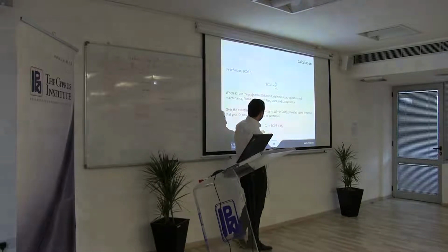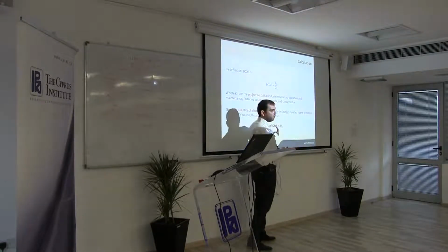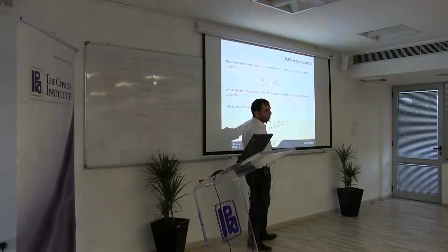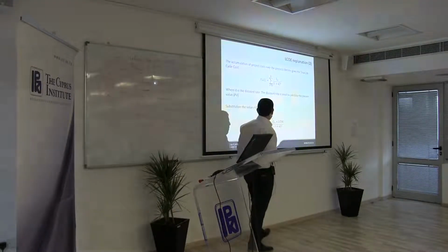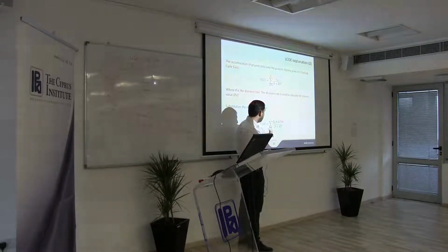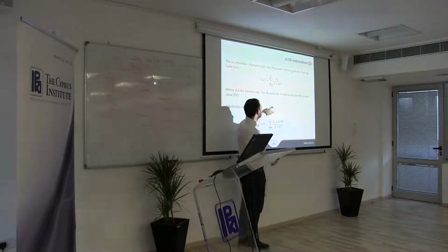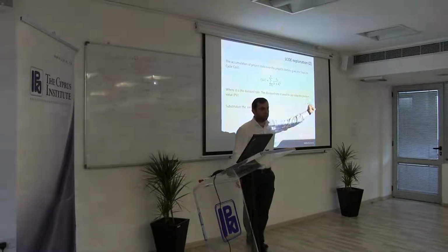And similar to what we did earlier, where we rearranged the equation here to express costs in terms of LCOE times amount of electricity, we can rewrite this equation in terms of generated electricity. So by discounting the amount of generated electricity times the LCOE, we get again the total life cycle cost. And as you can see here, the number of years starts from the first year, and that's because the electricity being generated only starts in the first year of operation. In year 0 here, we only have the investment costs. We have no electricity being generated.